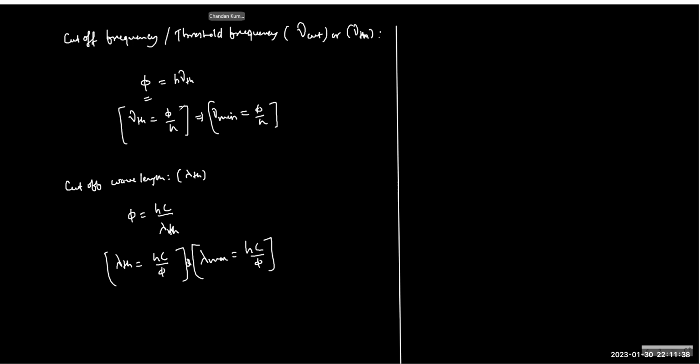Higher frequency or lower wavelength can penetrate deeper into the surface. And because we wanted to hit the photons in the PN junction depletion region, we kept the top p-type layer really thin, so that the photons can penetrate the p-type and reach the depletion region, where the electron-hole pair can generate, and that can be pulled back by the substrate to create the potential difference, which we can derive for power consumption. So that is what I discussed.